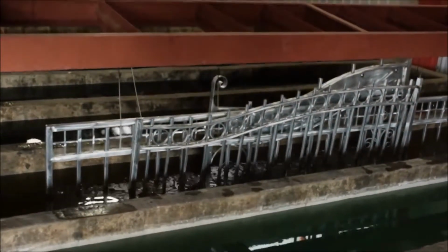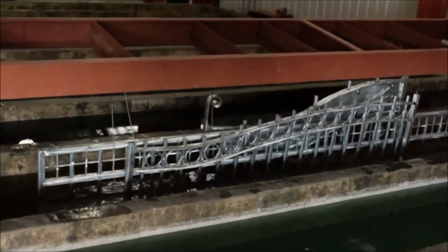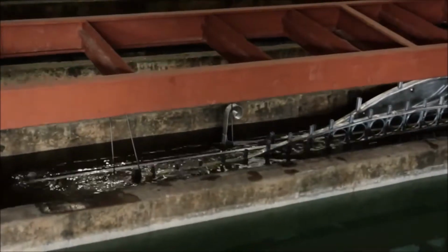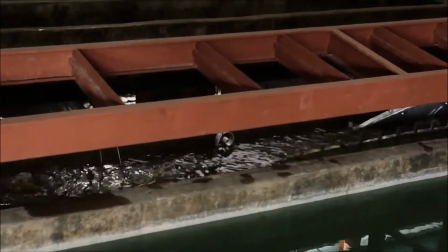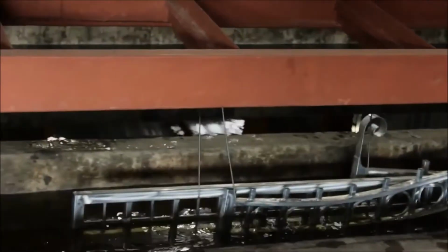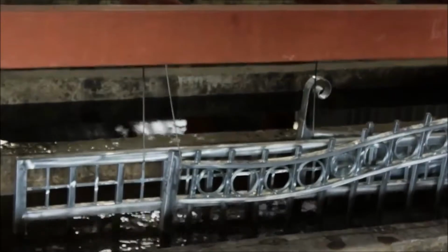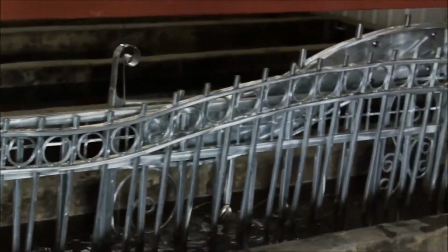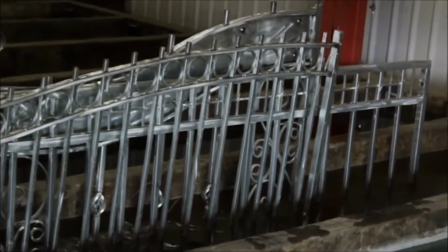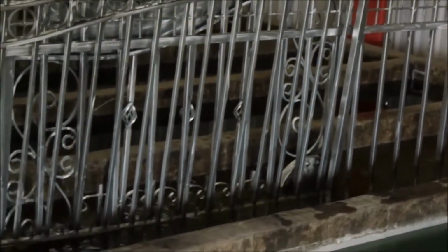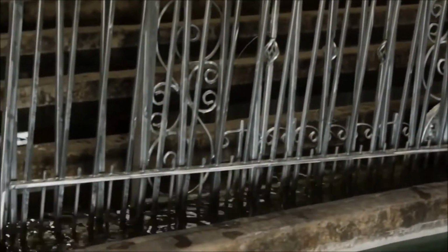The zinc phosphating is a very important stage of the painting process, because we need the powder to bond to the galvanized steel finish, the zinc finish. If we don't do that, the surface is too smooth, and over time the powder coating will peel off the zinc. There's lots of gate fences that I've experienced in America and Australia that don't go through this process, and after a while the paint just chips off very easily. Powder coating comes right off, because there's no bonding at all.